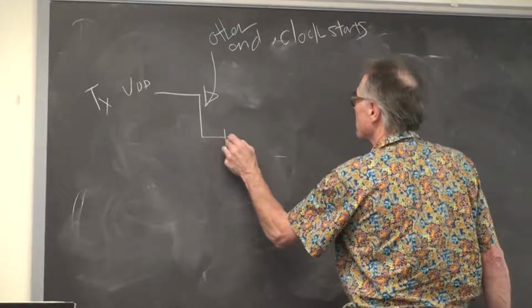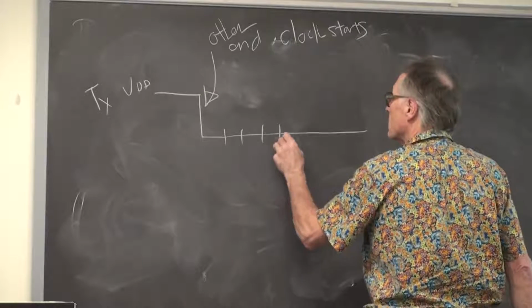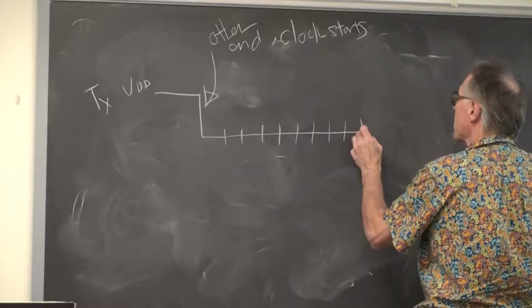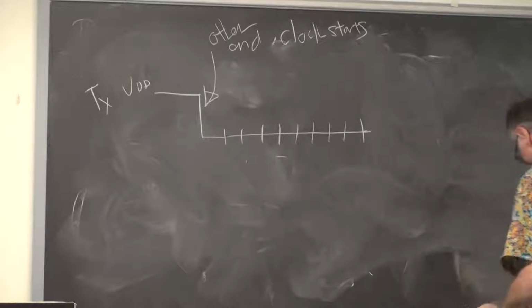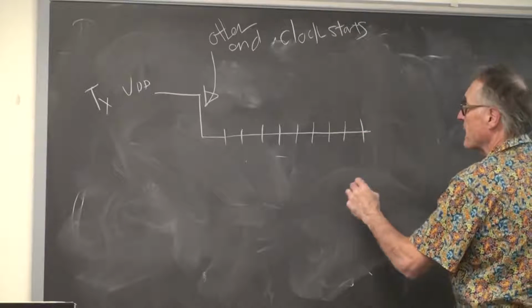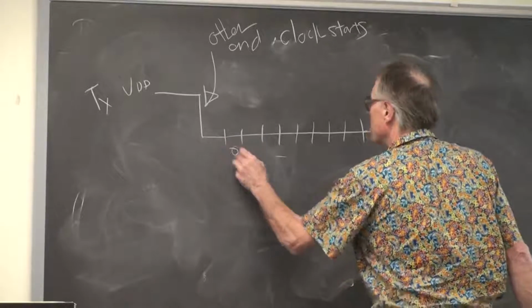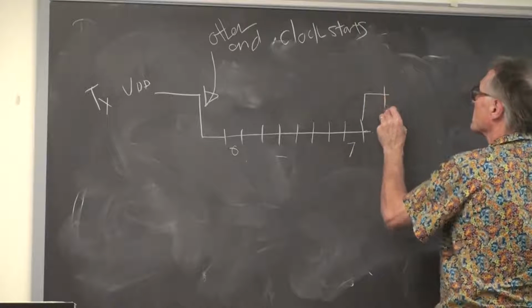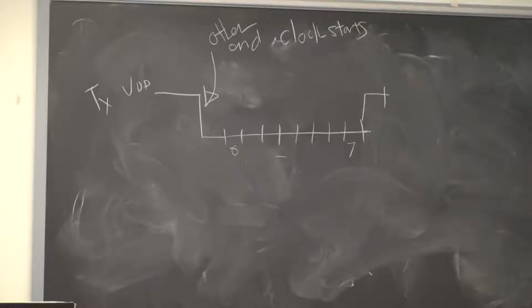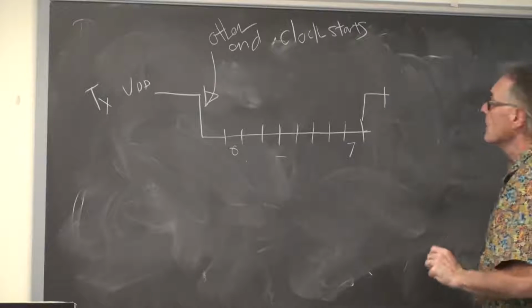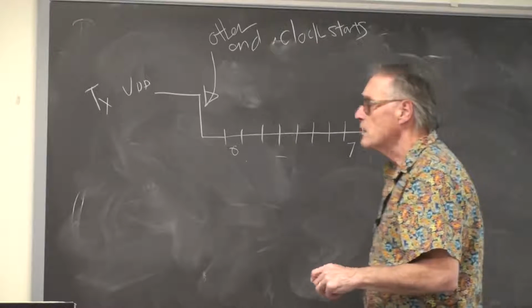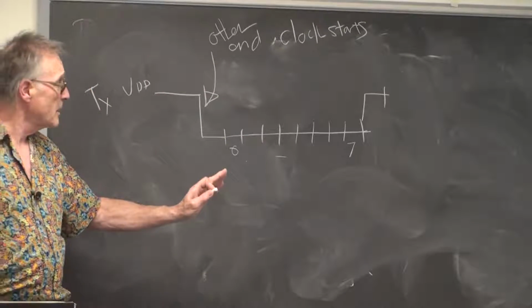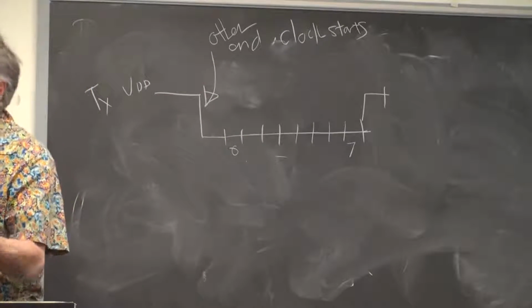Then the next 8 bit times send data from least significant bit to most significant bit. And then there is a stop bit, which is 1 bit long and is high, to make sure there is clock synchronization. So it's 10 bits total to send an 8-bit character.